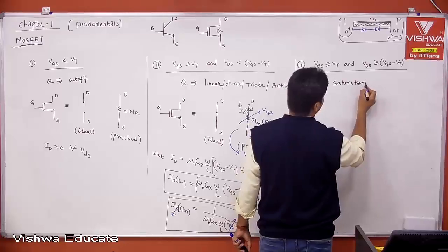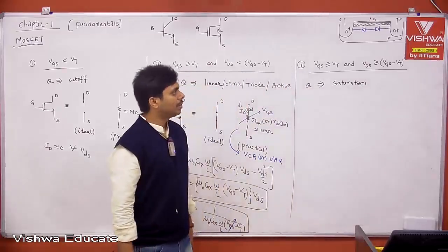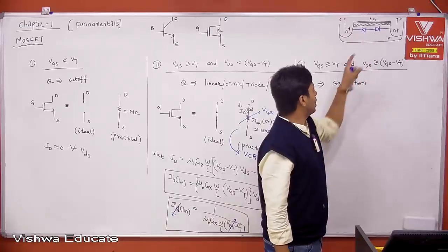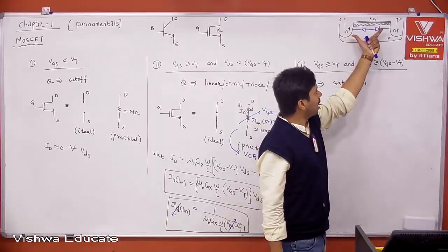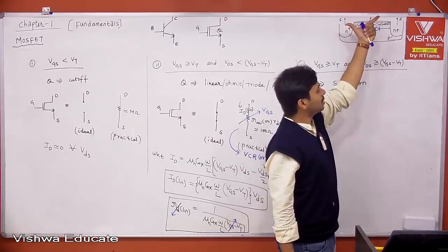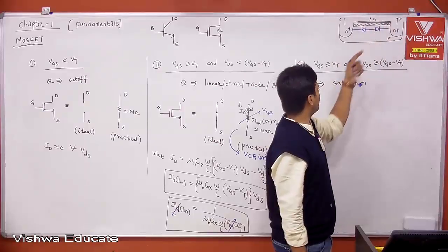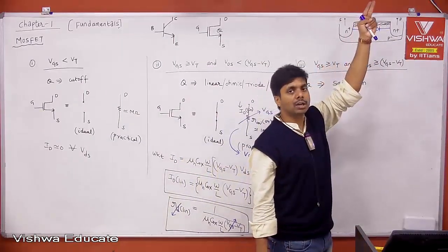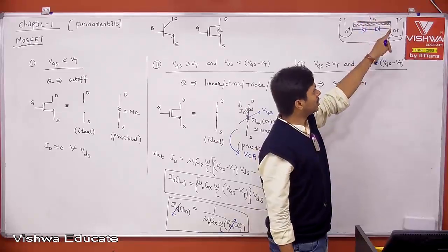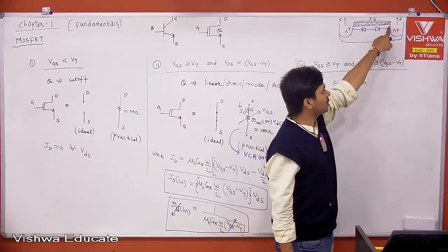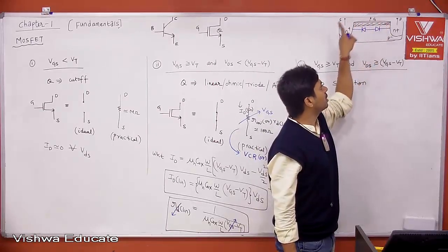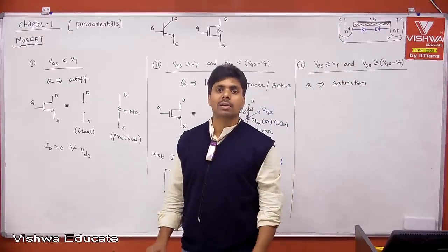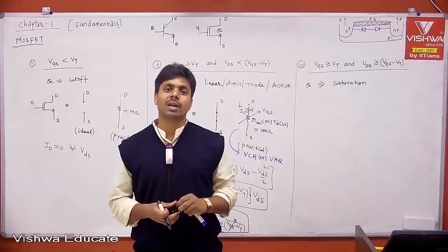The transistor is said to be in saturation region because when you apply large VDS, maybe after forming the channel because of VGS, after forming the channel, right, then when you apply VDS from 0, you will see linear current. That's why linear region. But as you increase your VDS, expecting the current to be increasing linearly, but because of something called pinch off condition which you see exactly at the drain, then you see the current which will be saturated.